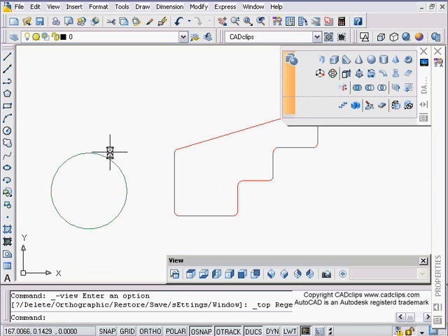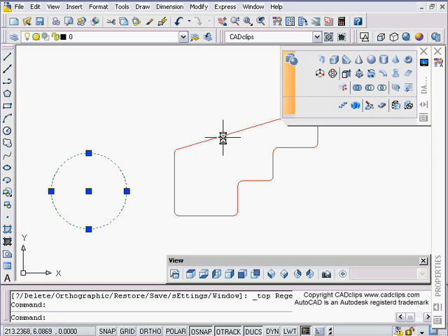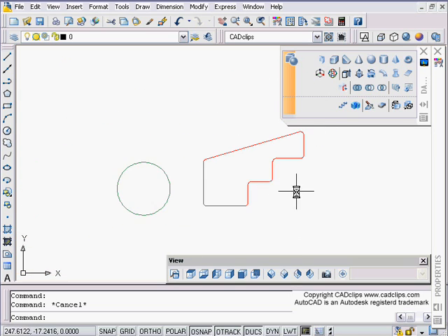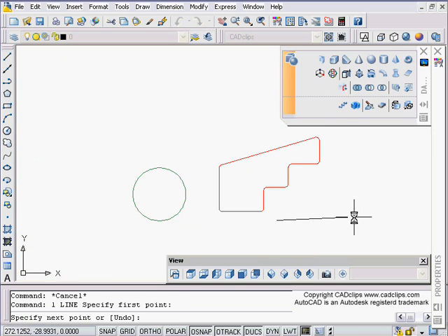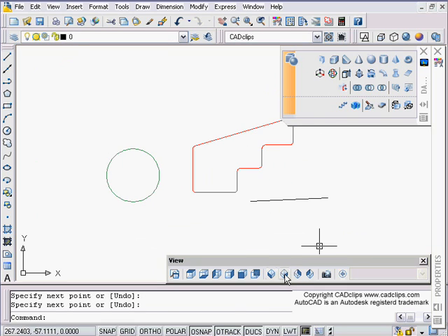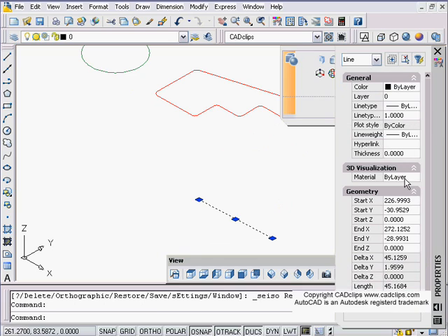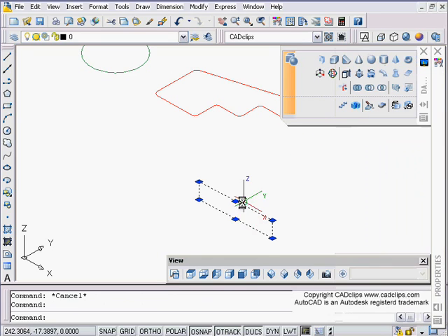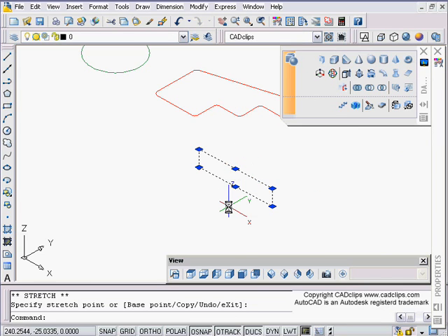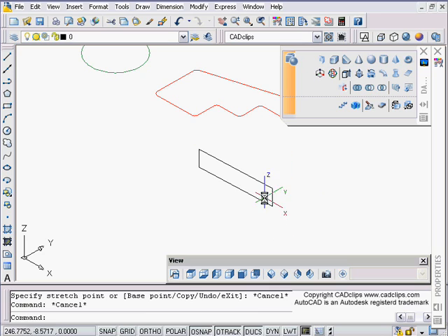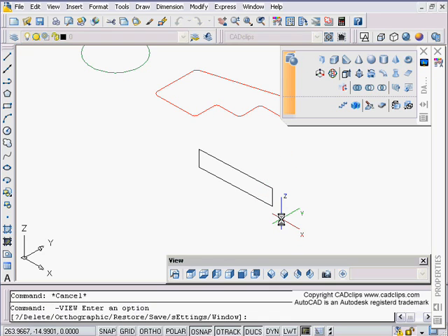And what I'm talking about with thickness, here I just have a circle that's got some color. This is a closed polyline that has filleted corners, and I can even just draw a line over here. It doesn't matter. Go look at that in 3D. Any object can be given thickness. If a line is given thickness, it just kind of springs up from there. After that you can move it around. It's a line that has vertical thickness, so it goes up in the Z direction.